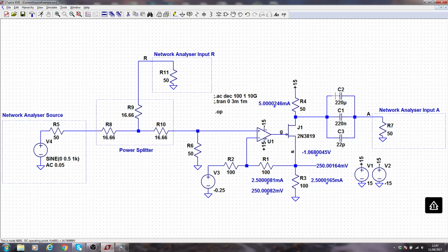The trouble with the electrolytic capacitor like that is they're spiral shaped, and they're usually physically quite large, especially if you want to withstand a reasonable voltage. 60 volts or so is quite common. Because they're spiral shaped, you get inductance effectively, and as the frequency goes up, the capacitor starts to look less and less like a capacitor, and eventually more and more like an inductor. And if you want high frequency signals to travel through inductors, you're going to struggle because the impedance of the inductor goes up with frequency. So we have to do something to try and make a better high frequency capacitor and low frequency capacitor.